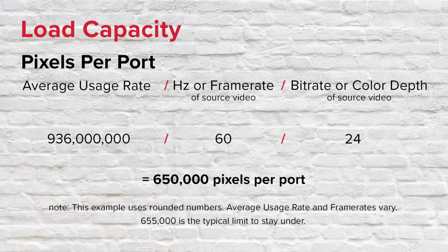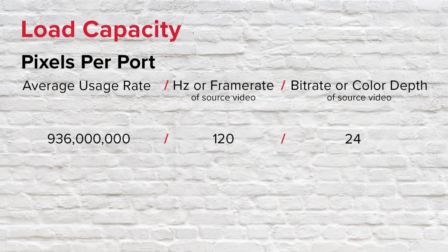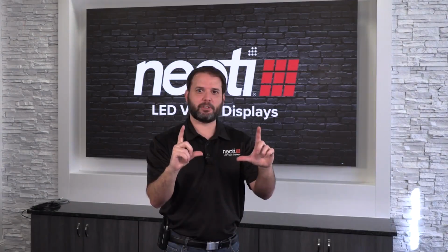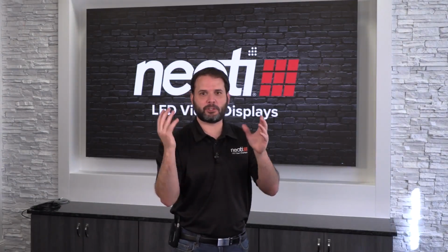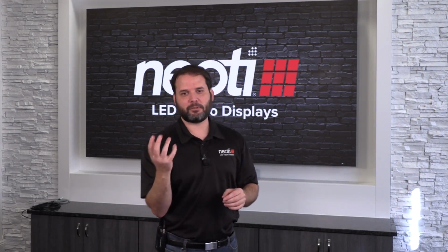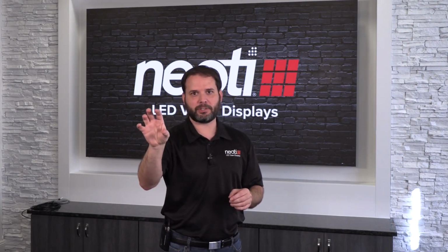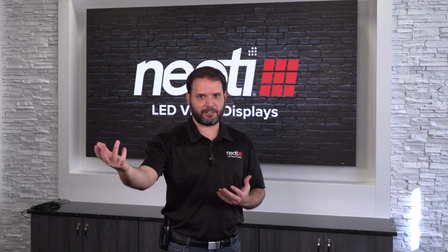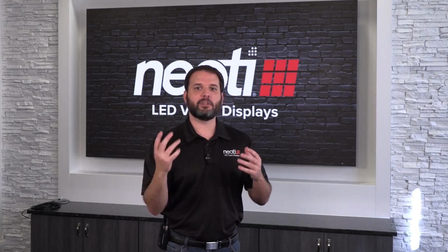That's your number. Now, as you change things, if you go up to 120 hertz on your source video, then your output gets cut in half. 655,000 turns into about 325,000, right? And so what that means is you have to halve the amount of panels you can put on your chain for that port, which means for the screen that you've planned on, if you change from 60 to 120 on the source, then you now have to provide double the amount of Cat5, Cat5e, Cat6, double the amount of Ethernet cables, and double the amount of ports.